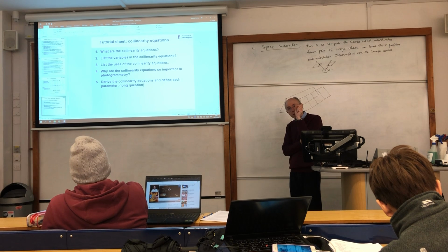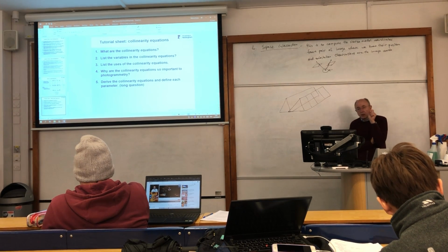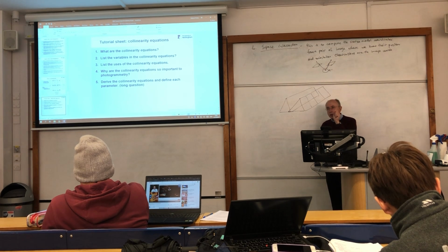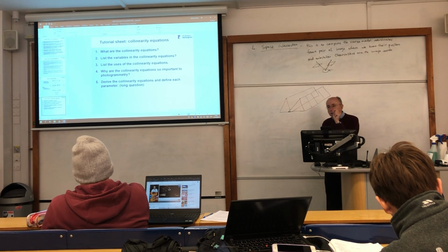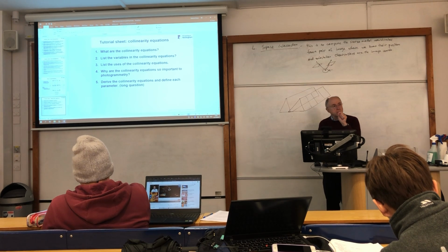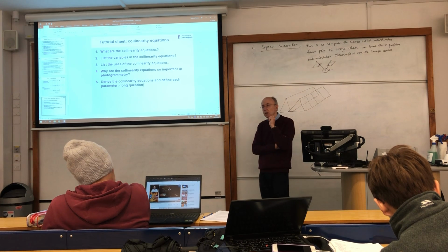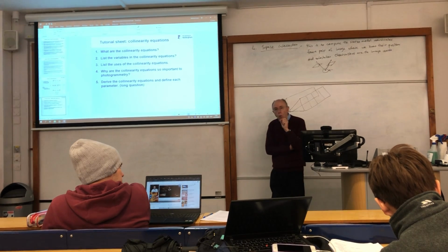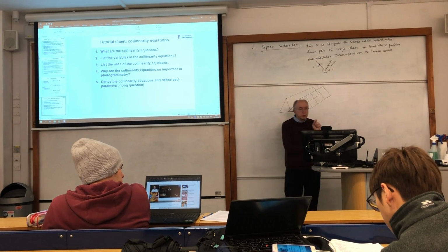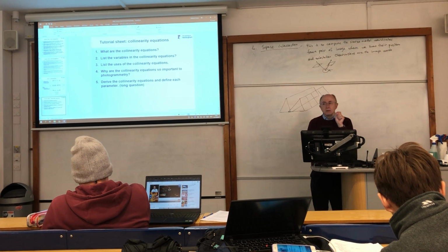Those 3 points, if the photograph is in the correct position and orientation, should be in a straight line. Right? If the position or the orientation of the photograph is not correct, they will not be in a straight line. And it's all of the points simultaneously have to be collinear.